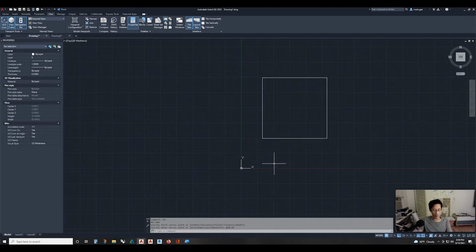Let's do it again. Let's draw one in the opposite direction. REC. Well, we start at that same point, and I'll snap to that there. We don't really need to move the mouse, but we can move the mouse just to give ourselves a preview. We'll say minus, how about minus 5, comma, minus 6. Enter. So there is a 5 by 6 rectangle. It started at that point. We specified that opposite corner.